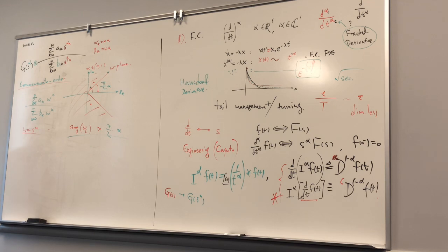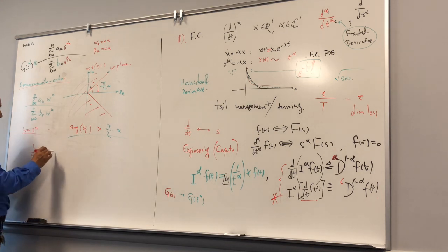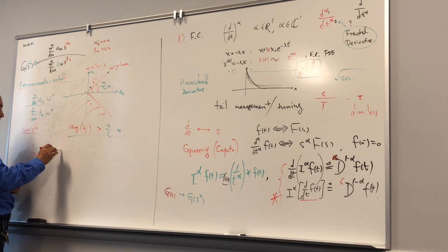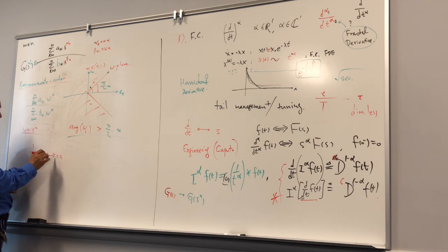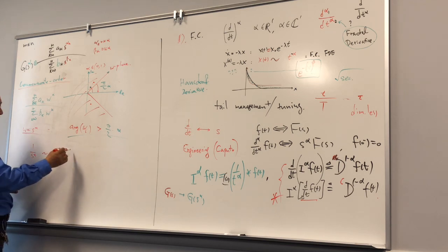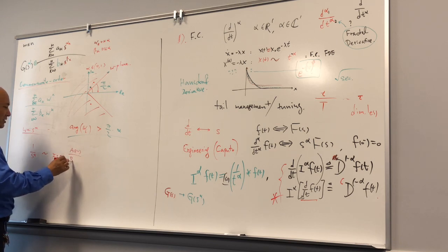But on the other hand, people feel that even in the simplest case, 1 over s to the power of alpha, the fractional order integrator, how can I make this into an approximate digital IIR, infinite impulse response, meaning you have A(z^-1) over B(z^-1).